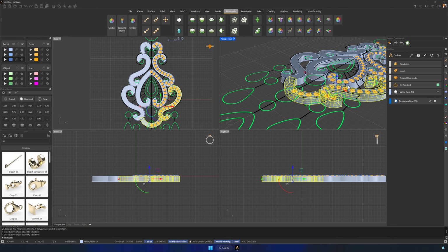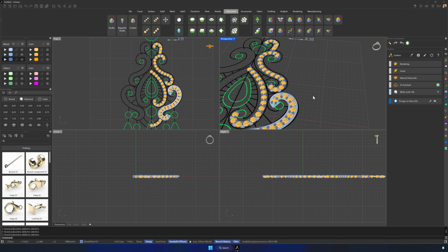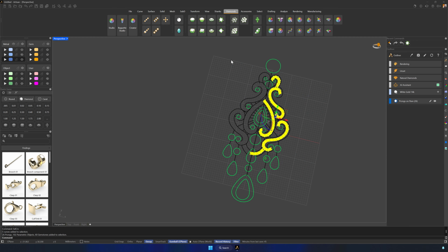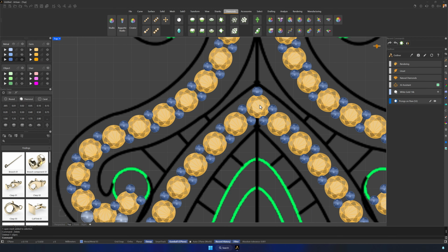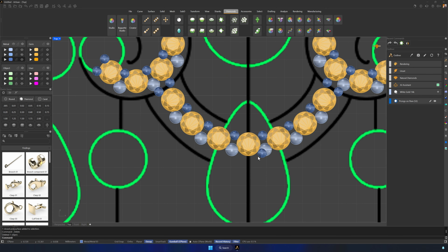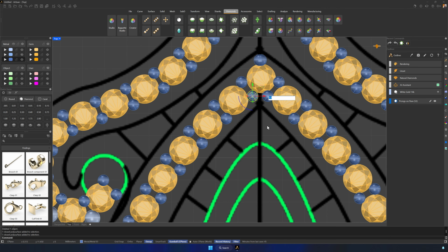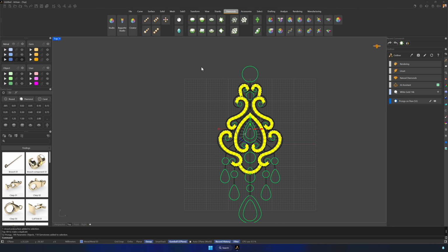Now we select the poly surfaces, move them to another layer, and hide them. We can delete temporary geometry and reorganize the layers. We select everything, apply mirror from 0 while holding Shift, and now the symmetry is complete. Some areas may be duplicated. But the rest is correct. We group everything and continue.